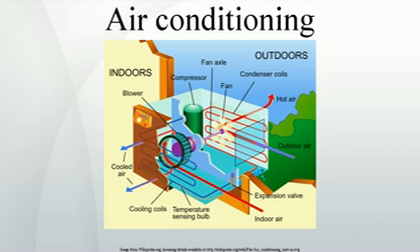However, single-hosed units cool a room less effectively than dual-hosed as the air expelled from the room through the single hose creates negative pressure inside the room. Because of this, air, potentially warm air, from neighboring rooms is pulled into the room with the cooling unit to compensate.